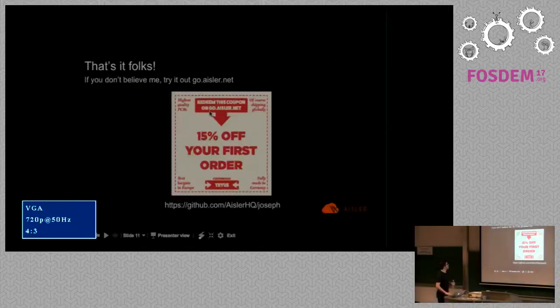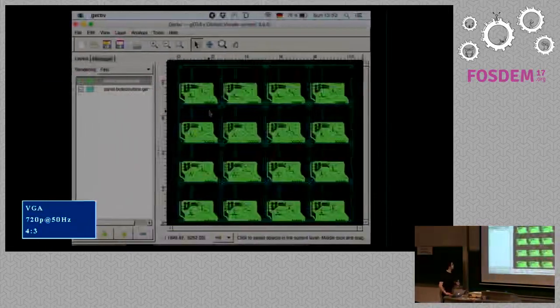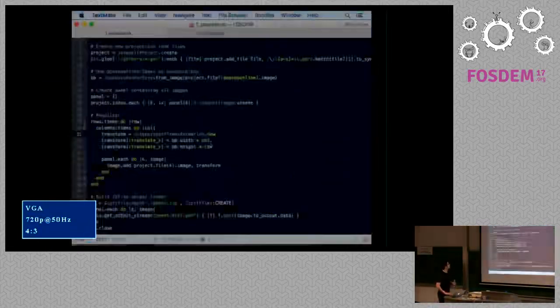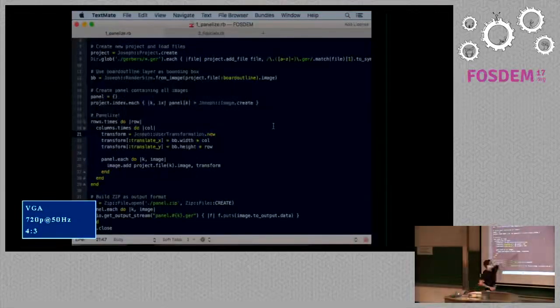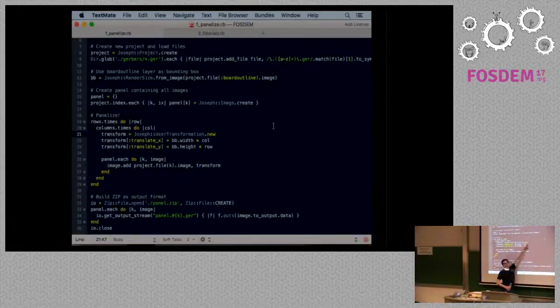Okay. Can you do that with script? Just add a little spacing, like more X, Y margin between the X and the Y boards. I mean, it should be scriptable, so you just add plus, and measurements are in inches here, and you have margin. Okay. That's a nice thing about scripting.